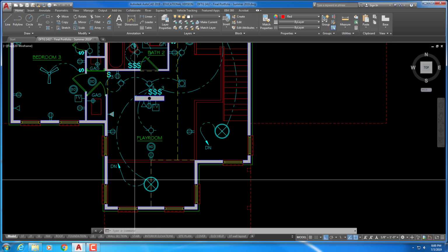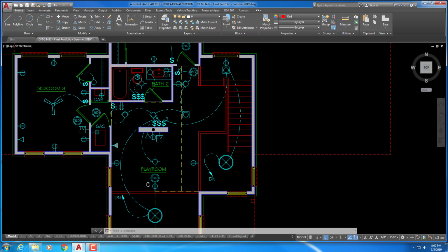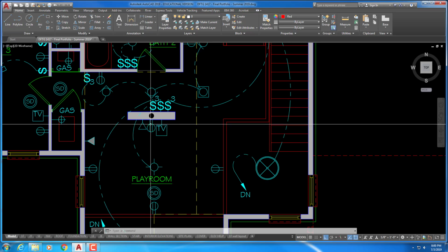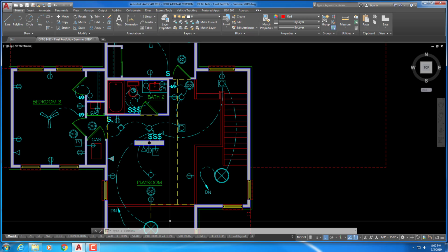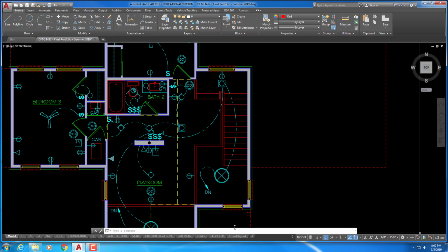And then this, of course, is centered in this space. And then we've got TV outlets and 3-way outlets. So there is, especially with the lighting, some organization where things need to be aligned. Usually it's centered between walls, so bear that in mind and keep in mind all the way through if it's lining up through the plan.